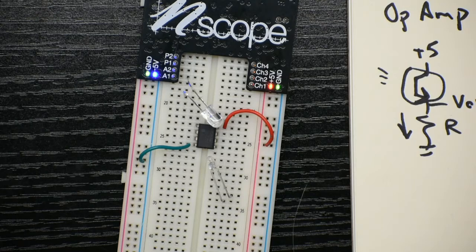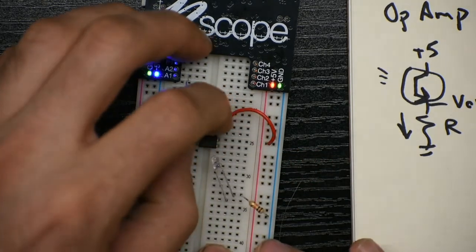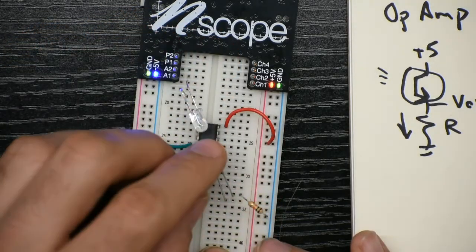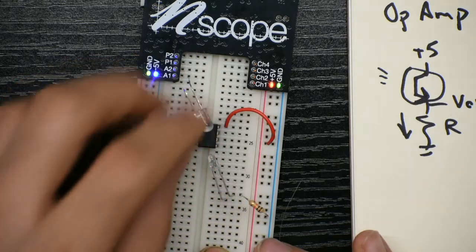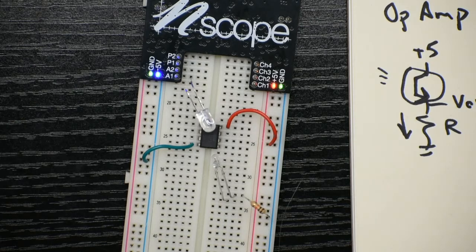So let me find some resistors. I'm going to put a 10K, and this is a little experimental, but I'll put a 10K in series with my phototransistor to ground, because I don't really know, this is going to be a lot of light from the LED to hit it, so the voltage might be pretty big. If I was just using ambient light, I'd probably need a much bigger resistor, like 100,000 or a million. But this will be a really conductive path right here. And then I'm going to use 330 in series with my LED, and that's to limit how bright the LED can get, so we don't burn it out.